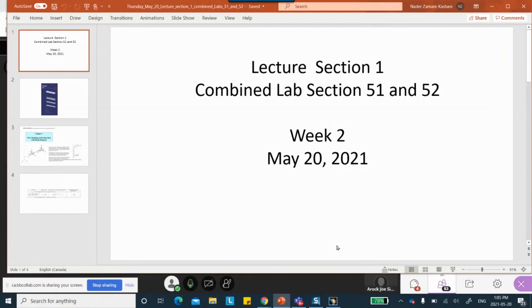When you have a single part and you create an axis, that axis is kind of attached to the object. So I know what you're thinking. You're thinking about what if I had something that was stationary, a global axis. Immediately it becomes two parts: one that you don't want to move as a rigid body, and something that is fixed in space. But you can't do that. Don't go that route. Just don't go that route.